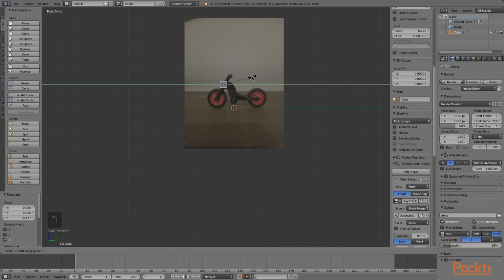So now we're going to scale it on the y, so you're going to press S for scale, Y for y-axis, and then it's going to let you scale it in, make it a little thinner. And then we're going to do rotate for R. You're going to click R for rotate, and we want to rotate it on the x-axis to kind of give it that diagonal rotation there. So I clicked R for rotate and X for x-axis, and now I'm just going to bring my mouse down and put it right there where it kind of looks like it's right there. And there we go. We have our first piece.